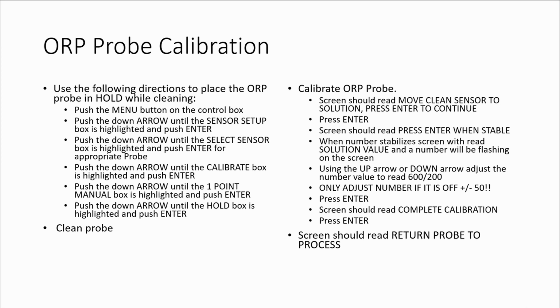We always use hold, but before this, we basically put our pumps in hand. That way, nothing you do to this controller will change the chlorine dosage. But in this situation, you leave the chlorine dosing pump in auto, but you've changed this to where you're holding the dosing rate signal coming from the controller.